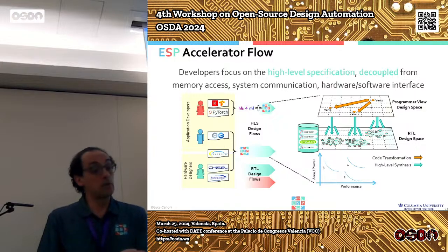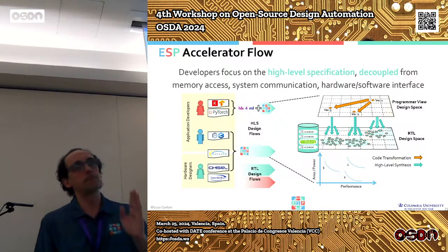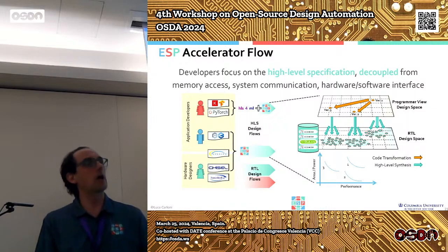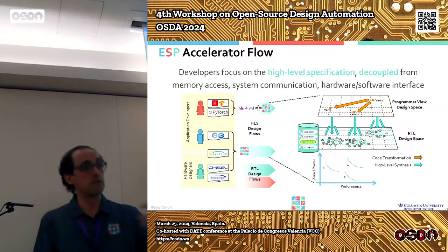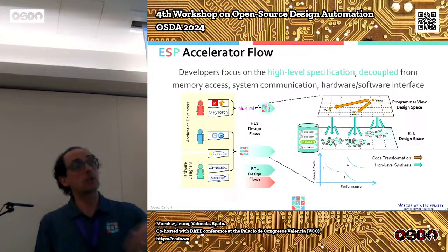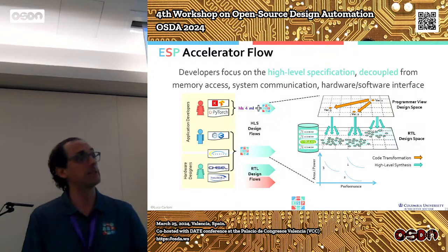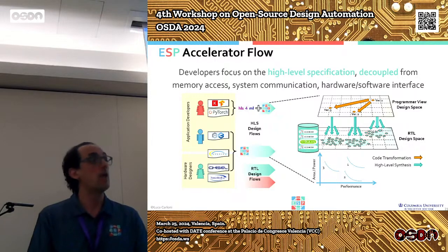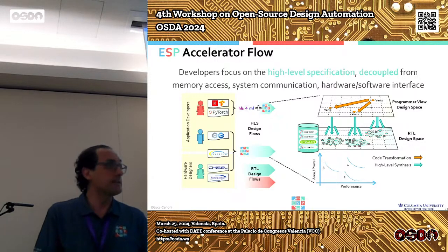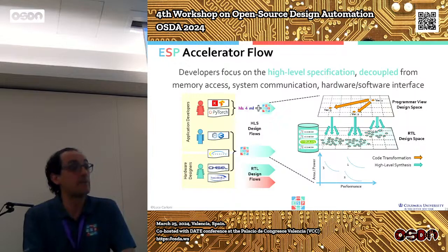But when you have developed one particular version of your accelerator, maybe you still don't hit the exact performance and area figures that you want to meet. So then, certainly you need design effort. So you go back to your C, C++, SystemC, and you try to change the architecture. But again, you rely on high-level synthesis to obtain many different implementations from a single specification. And this is what we really teach to try to make design for usability.